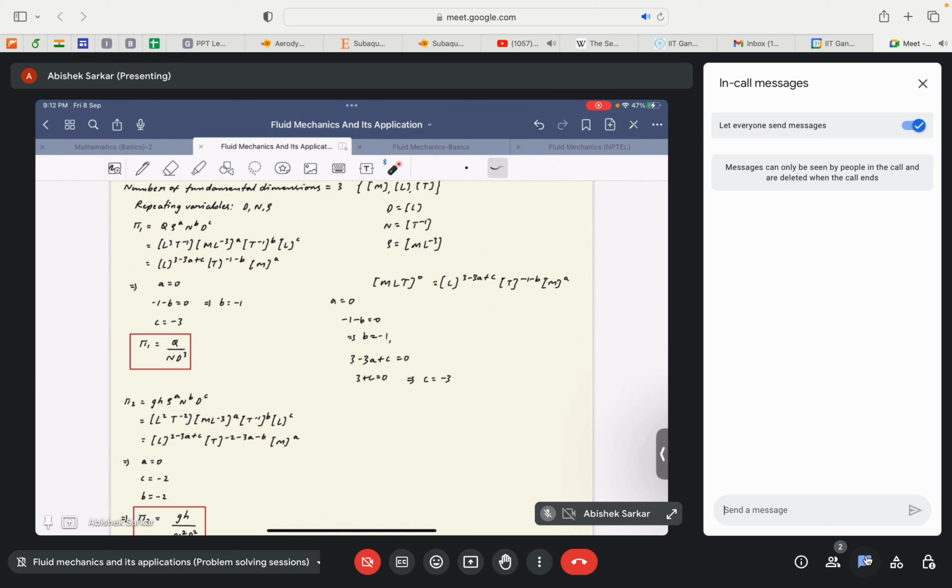The second approach, the scale factor approach, is a more generalized version of the previous one, where having an idea of the driving forces helps us determine the scaling rule, or modeling rule, that gives the non-dimensional number we need for getting the parameters of the prototype or the model.